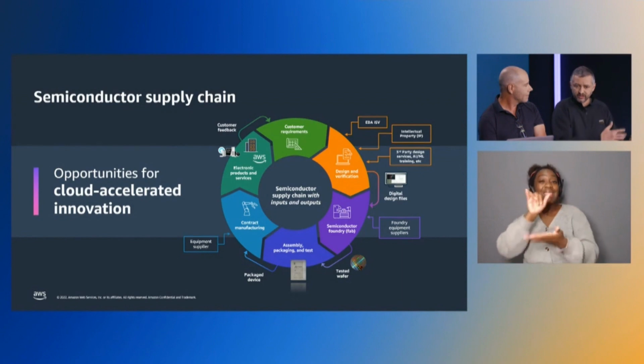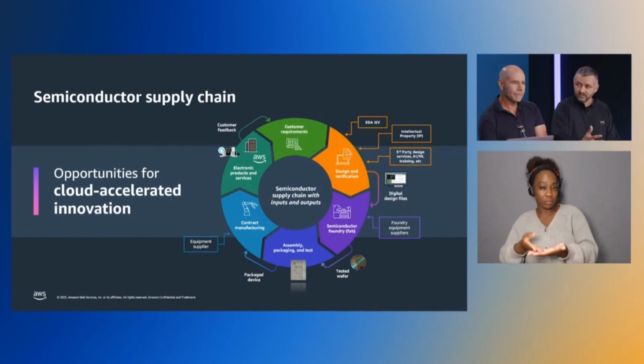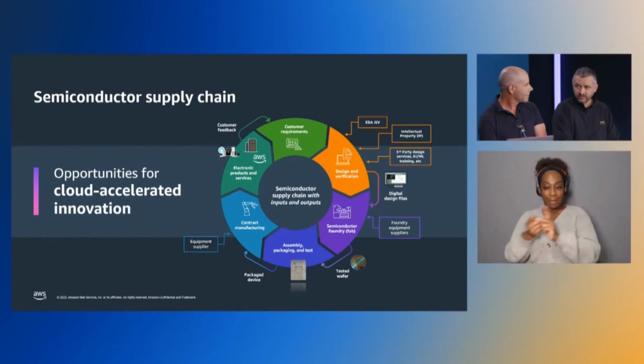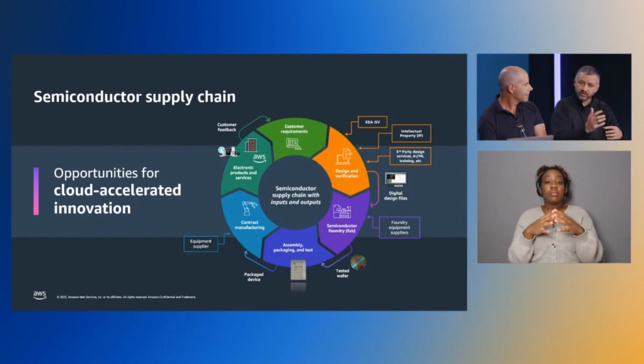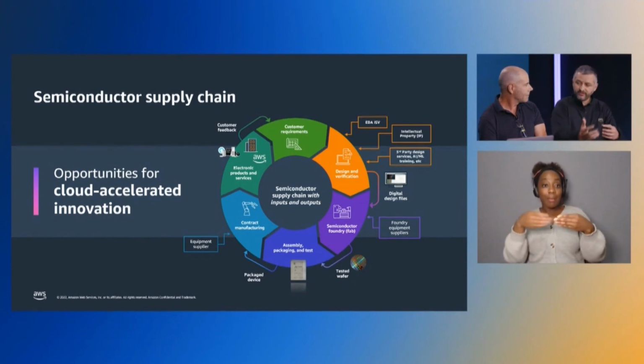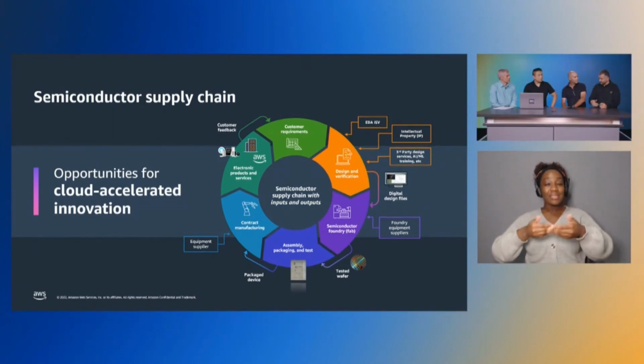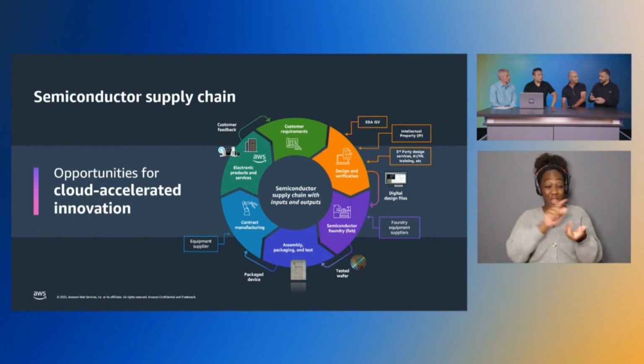And then after that, for your digital building blocks, you go through a synthesis stage, which translates the code that you wrote in these descriptive languages, Verilog or SystemVerilog, into actual gates. Now we are going into the manufacturing phase. You have selected the process that you are going to use, the foundry that you are going to manufacture your chip at, and now that translation process is the first stage of getting these details in.